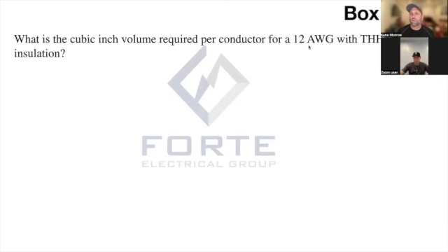Can you see this whole question, or are we in the way? No, it's fine. What is the cubic inch? Now, what they're trying to do right here is throw you off with insulation. Insulation means nothing when you're finding box fill. The only thing that you're worried about is the wire size. Right.